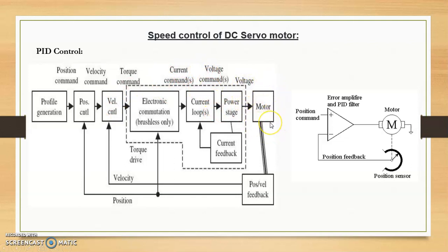The simple explanation of this block diagram is, we have a reference value and we have a PID controller, which has a proportional and integral parameter and also the derivative parameter. The signal received from the motor for each step is collected from your encoder, which is sent to your comparator, or your error generator. There the position command signal and the feedback signals are compared, and the error signal is amplified and sent to the PID controller, and that PID controller is going to control the motor operation.